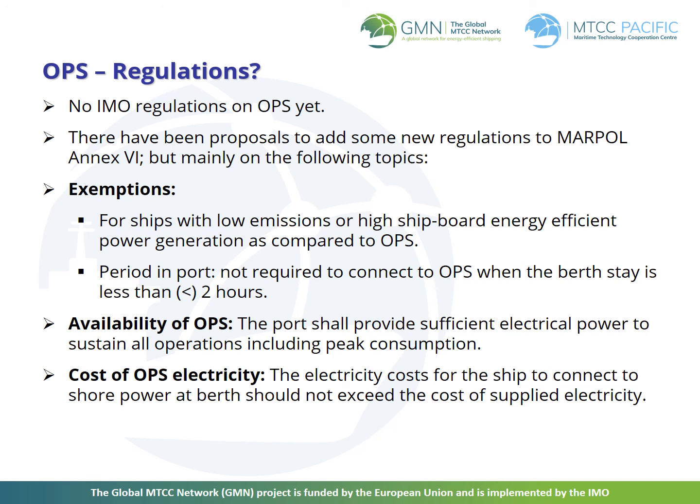No ship should be required to connect to OPS when the planned port stay at the actual berth is less than a couple of hours. The port or terminal should provide sufficient electrical power to sustain all normal operations during the port call, including calculated peak consumption. The cost for the ship to connect to shore power at berth should not exceed the average comparable costs of port services in general and the cost of supplied electricity to shore-based consumers within the vicinity of the port or terminal.